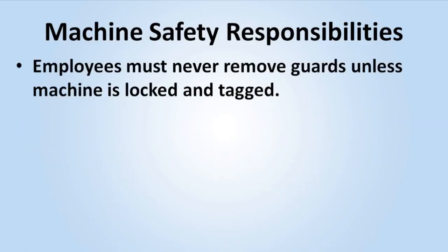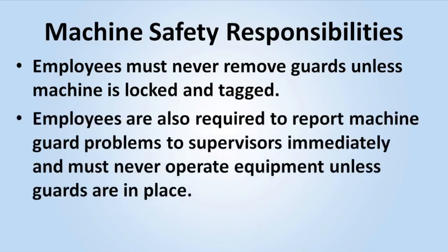Employees must never remove guards unless the machine is locked and tagged. Employees are also required to report machine guard problems to supervisors immediately and must never operate equipment unless guards are in place.